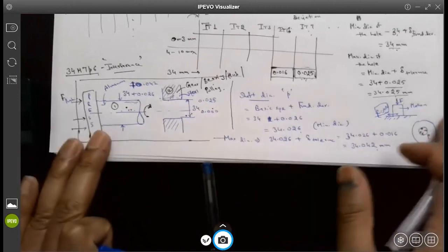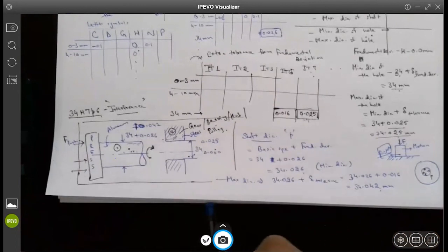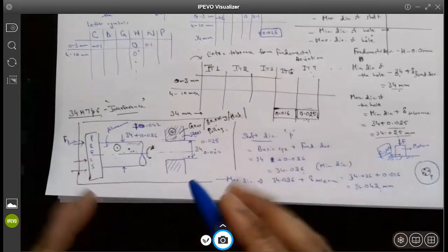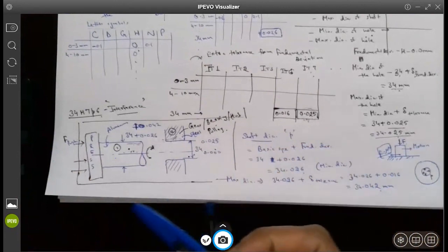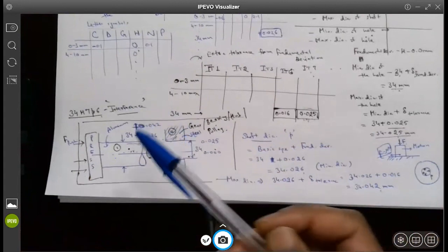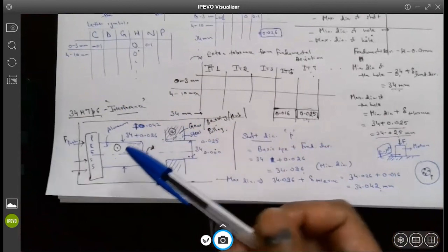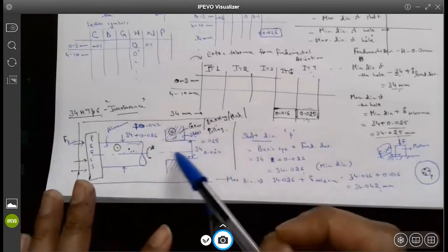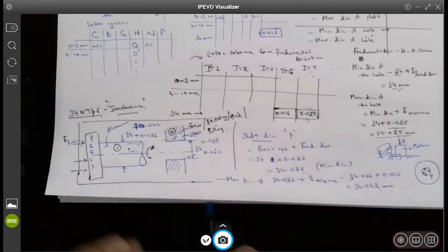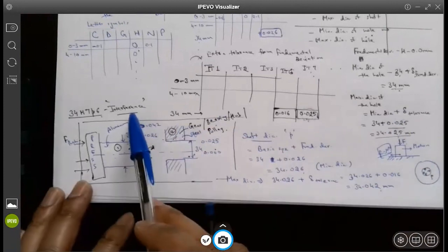What will prevent the slippage? What is the condition of that slippage? We will actually come to this discussion. I just wanted to lead you to this topic to make sure that we understand the reason for going to interference fits, what the consequences of interference fits are for the component, what type of stresses are going to come, and how much the torque carrying capacity would be for an interference fit. Those are the questions we will revisit in our next lecture, but hopefully this will give you an idea about the issues you need to worry about as a designer for an interference fit.